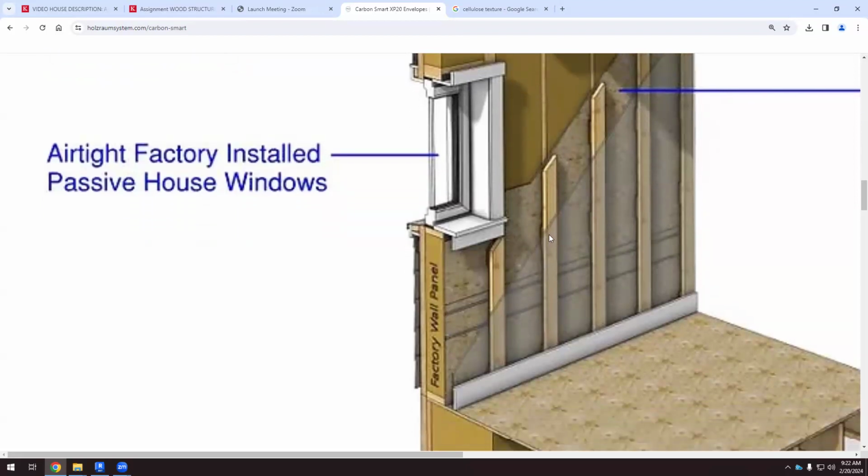So the interior finish can be a gypsum wall, or it can be another plywood or whatever, but that's the interior finish. And we have a cavity, and that cavity goes well because it helps me work with wires or small pipes or whatever. So we always have a cavity here inside. And I can fill this cavity with thermal insulation. That's a good thing. Or we can use this cavity for wiring the whole house. So it will be hidden behind the internal finish. Okay. So let's do it.